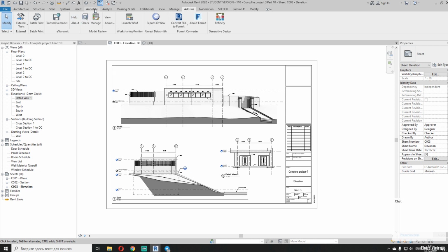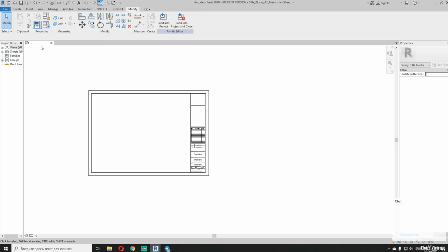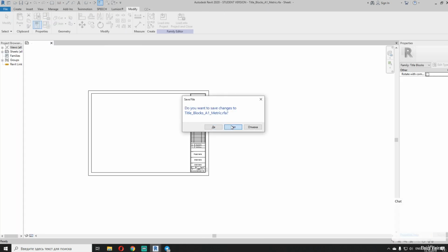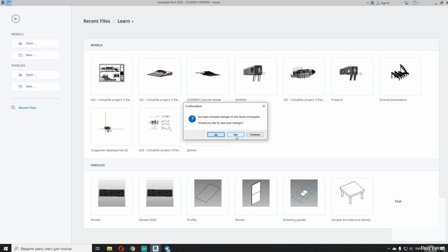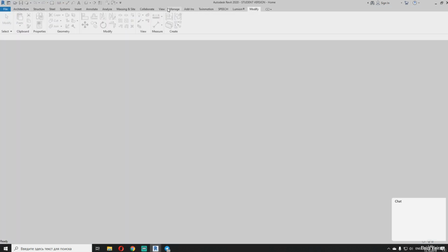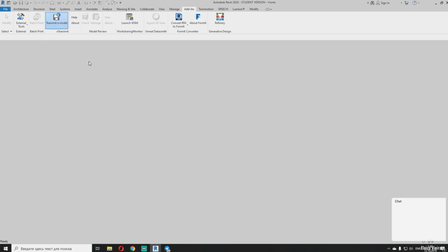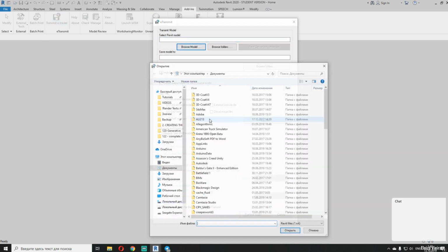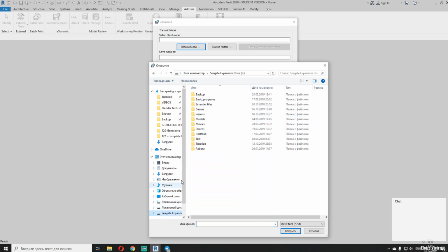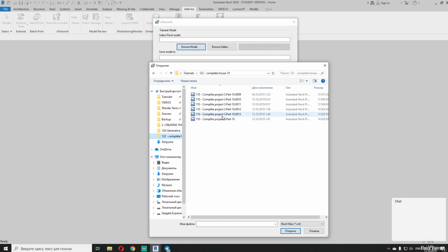Oh, we should close the project. I will close this project, and I will transmit this project. So don't save any changes. Add-ins, transmit projects, browse your model. Let's find our model. I think it's here.